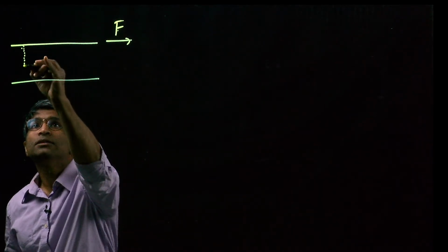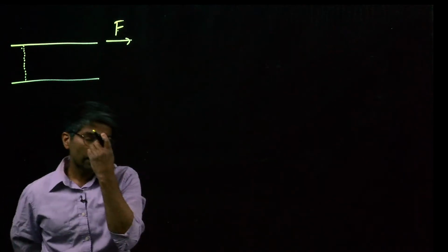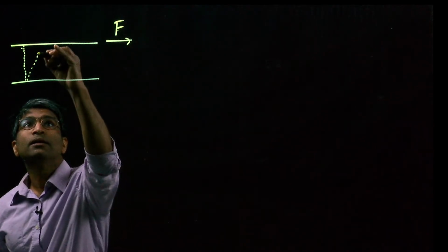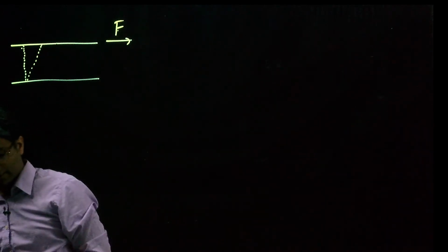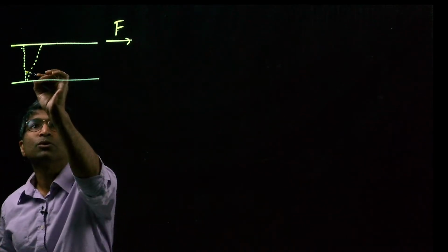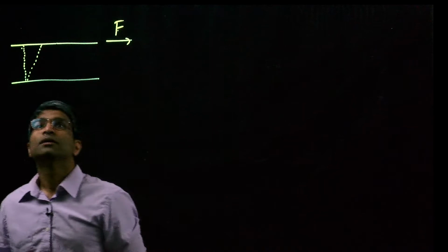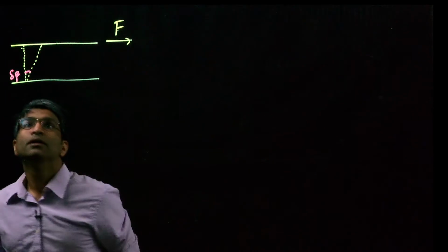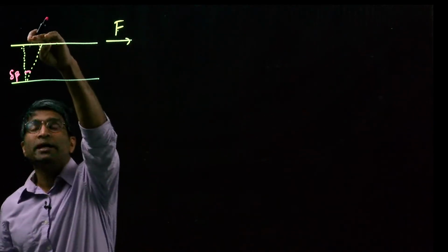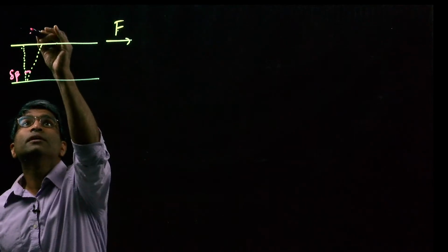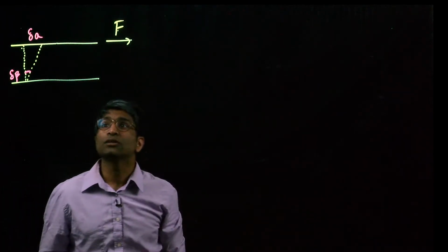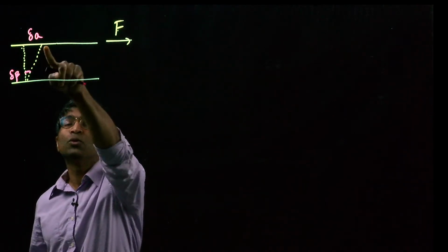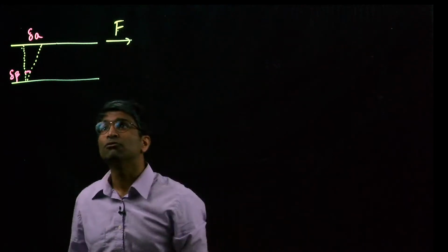And if I looked at some plane in this direction, that would presumably deform by some small angle given by delta beta. And at this top plane, that's going to result in a deformation delta A. So that's my original plane here that's moved over there as a result of this external force applied.